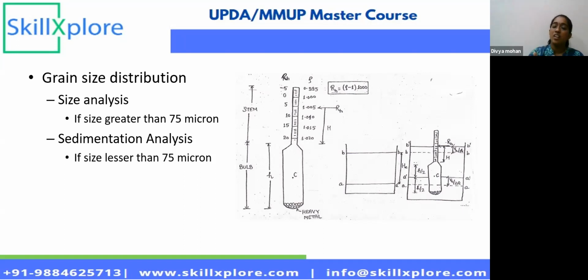Sieve analysis mainly employs gravitational force and vibrational force to separate the soil particles based on their sizes. However, the sedimentation analysis uses settling velocity of a particle size.